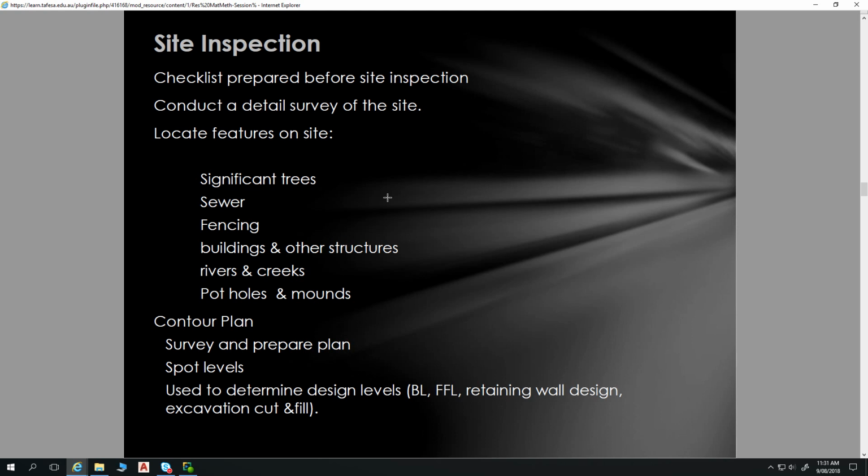So for all of your online resources to gain all that information, I've previously drawn up indicative house plans straight from Google Earth. I get the image, put it into CAD, scale it up to some known dimensions, and then draw up these things. And I've been about 100 millimeters out. Maybe that's a fluke, I don't know, but you can actually get some relatively detailed stuff before you even go to site and do any measuring up.